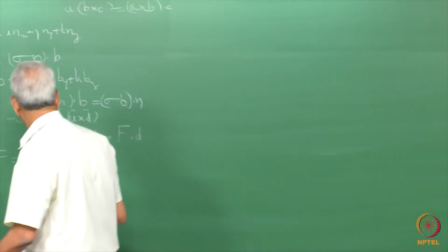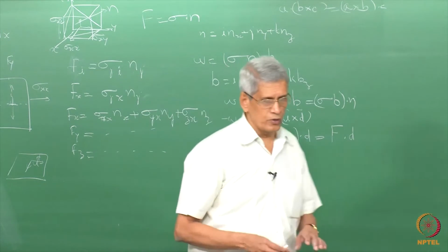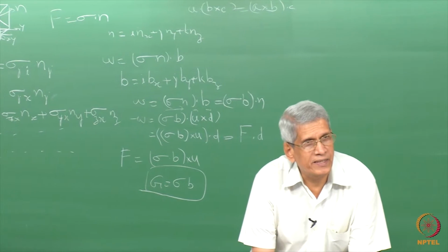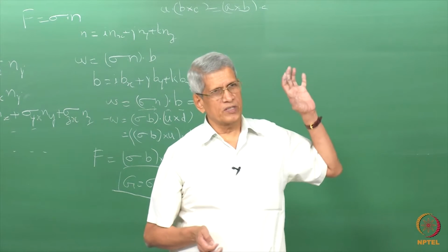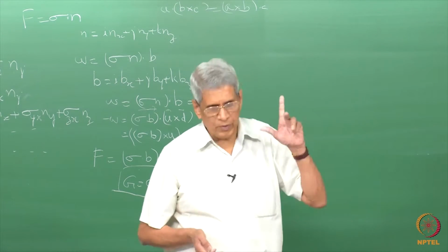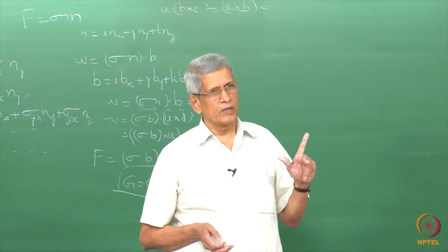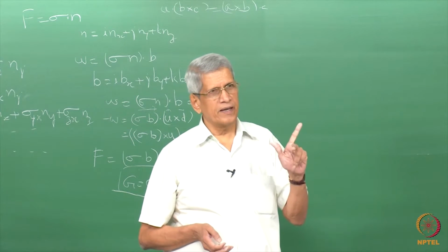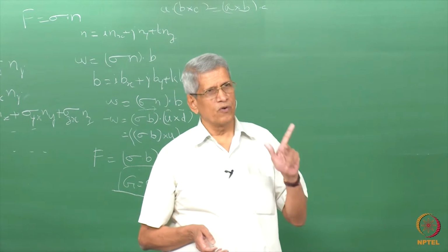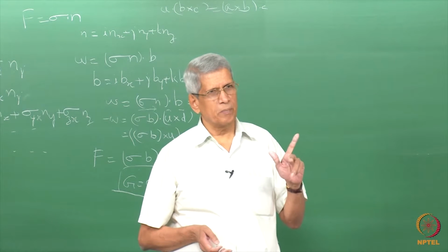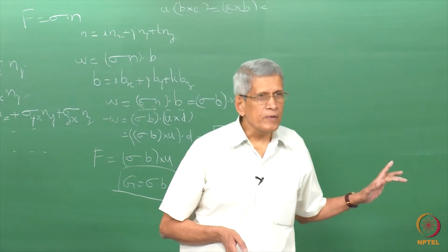So if this is clear, now what are the terms which we should know about the forces which are acting on the dislocations? It's a generalized expression which we have derived. If you know the components of the stress which are acting in different directions with respect to a crystallographic system which we have chosen, we can find out the force which is acting across the Burgers vector direction and also the force which is acting in the slip plane on the dislocation line. We have derived that expression.